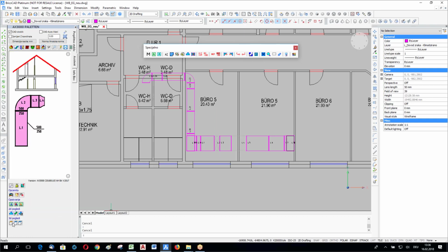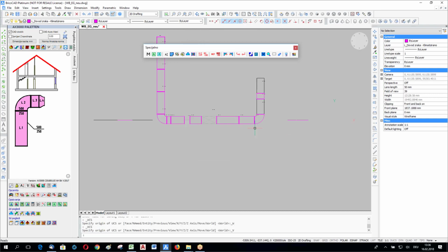To generate a 3D view, you have to do this the same way as for 2D views. My first point is, I need a name, maybe A is the name of the view. The first point should be at the left side. The second point should be at the right side. This is the point you are standing. The third point is the depth of the view, and everything in front of your 2 points and behind the third point will be invisible, and also the viewing will be rotated.